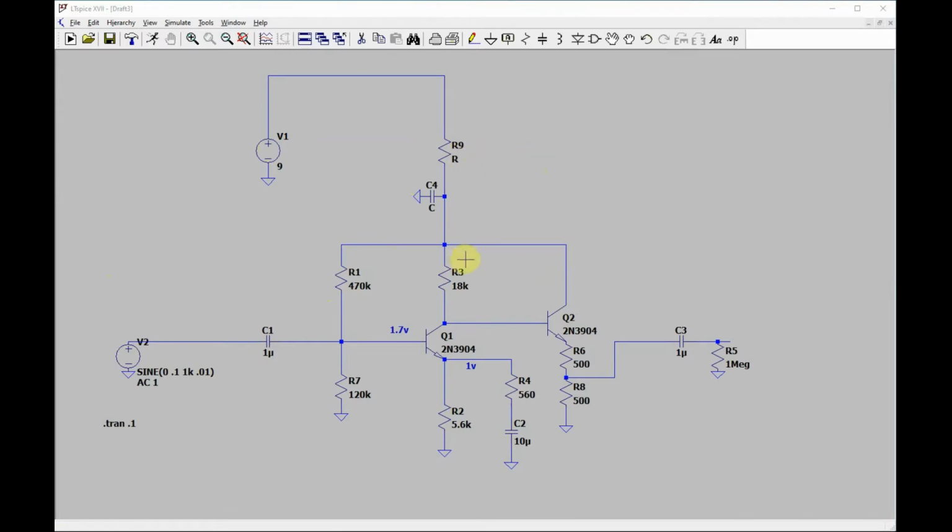Basically, you got 9 volts here, and you built this system around 9 volts, and so you don't really want to lower this voltage very much, because if you do, then it makes it appear as if it has less than 9 volts here. So you got to make this resistance substantially lower than these resistances.